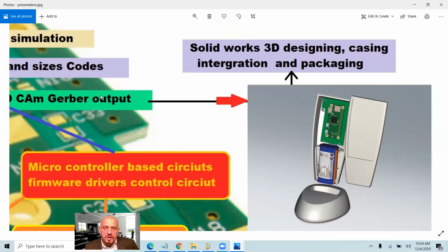Your PCB layout should be compatible with that. So either they will send you this, or somebody else who is working on it is going to share the mounting holes and sizes. Is it going to be a 3 mm screw? Mostly there are 3 mm screws inside the PCB.